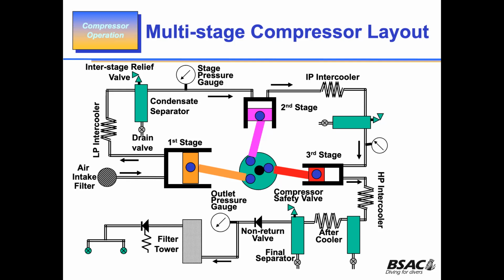And all we're saying now is that I put atmospheric air in at one end, and over 3 stages of compression, I get air that's been conditioned, cleaned and filtered going into my cylinder at the final pressure I want it. These compressors operate at anywhere between 230 and 300 bar. But the higher the pressure, the longer it takes to fill a cylinder with a small compressor.